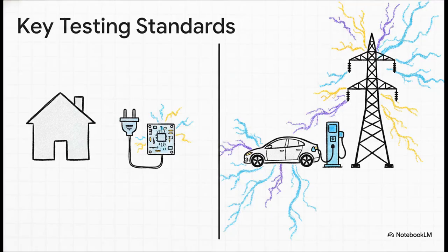Now, the main standards you're going to run into are IEC 60112 for your standard low-voltage tracking up to 600 volts. So that covers your typical PCBs and everyday household appliances. Then, way on the other end of the spectrum, we've got IEC 60587. This one is for much more severe, high-voltage ambient conditions, which is absolutely critical for modern applications like electric vehicle infrastructure and heavy-duty power grids.